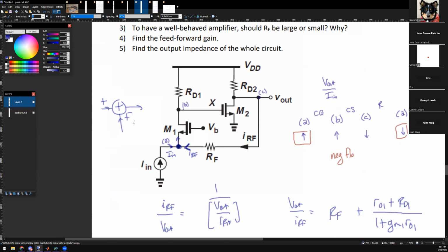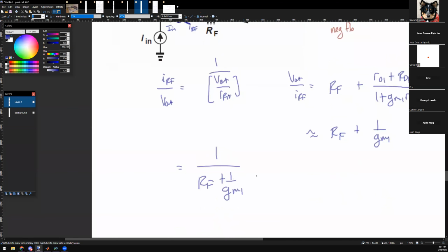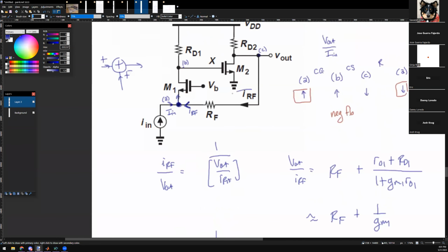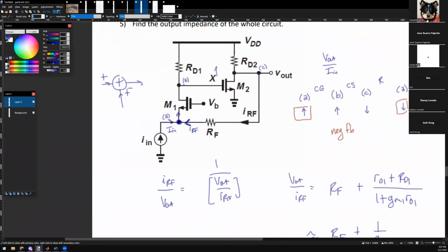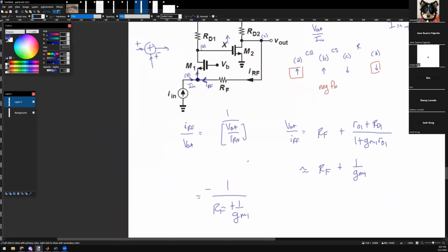So I need to negate this guy twice. So then it's negative, unfortunately. That's just because he put RF this way. Realistically, if this voltage goes up, the current sinks more in here and IRF actually sucks current away in this direction. The way your professor put IRF implies it's positive feedback, even though it should be negative feedback. So yeah, fine, whatever.